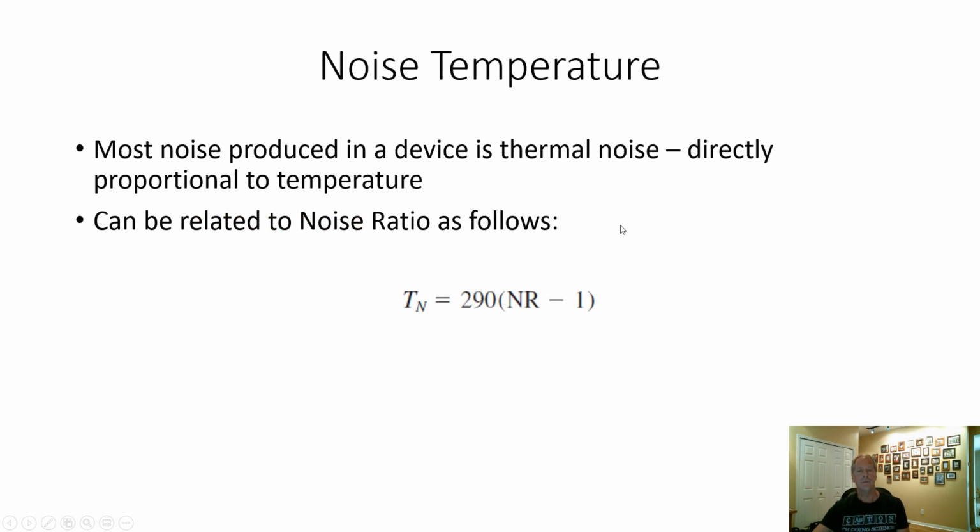Noise temperature, if you have a device that's getting hot, you take that noise ratio, minus 1, times 290, and that is your noise temperature. Another way of expressing noise.